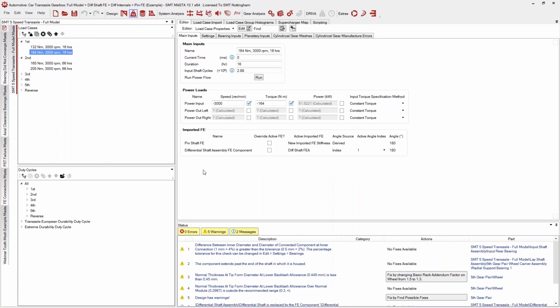This one currently works with only the input speed and torque specified, but as I say, if it's got 2 different paths of power going through to the different outputs, then you may see a problem here. And then what we can do is just specify this one power output. And in this case, I want it to be approximately 50%, so we can do minus 25.5. And then we can run that and it will calculate nicely.